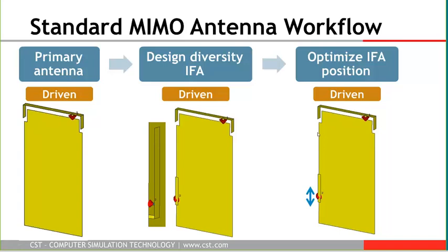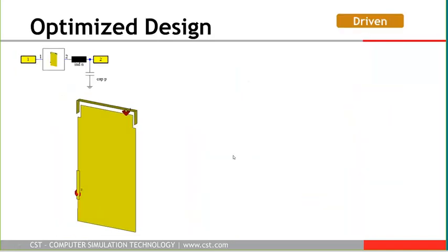So you know that if you will be maybe closer with the second antenna to the first antenna, there will be higher coupling than if you orient it a different way. To do that, there is a 3D model which has been simulated with frequency domain solver, and we need to match the second antenna in order to have an optimal performance of this antenna.